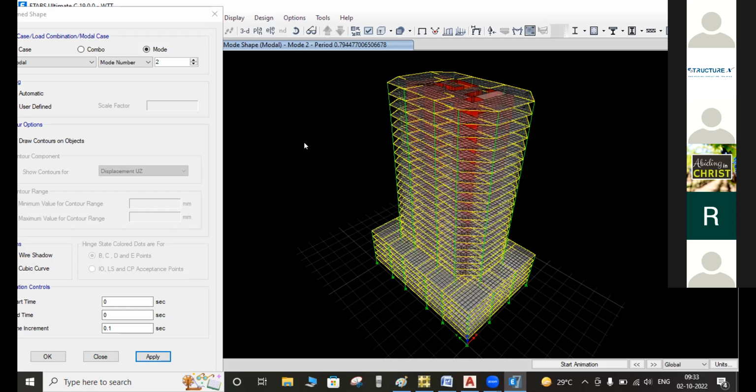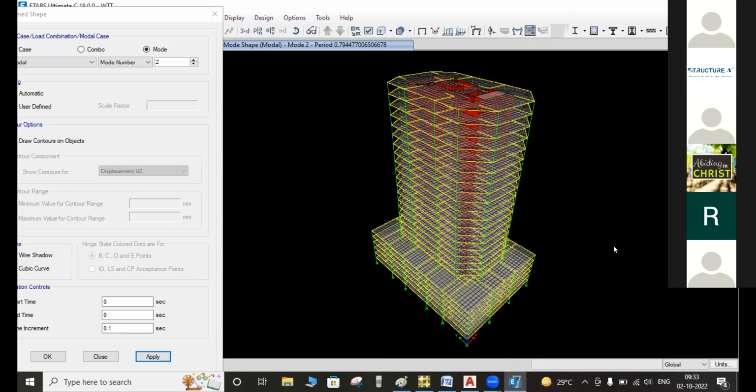That's why we perform this, and we provide shear walls or columns to control it. Okay, so these are important parts. So for the second mode, what will be the response? The second mode will also be translational. Translational and rotational, or pure translational? Basically, the starting two modes are pure translational, and the third mode will become the torsion.